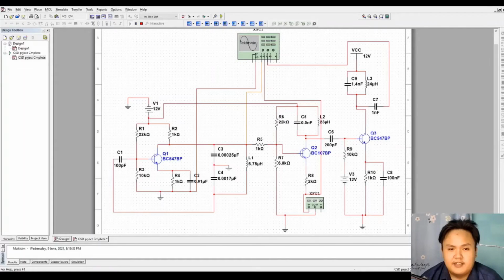We know that the signal classification for carrier and message frequency is a periodic signal, that is a sinusoidal signal. For the carrier signal, we use a tuned oscillator, this Colpitts oscillator. In this Colpitts oscillator, this parallel tuned inductor and capacitor tank circuit determines our carrier signal. We adjust the value until we get the desired frequency needed.